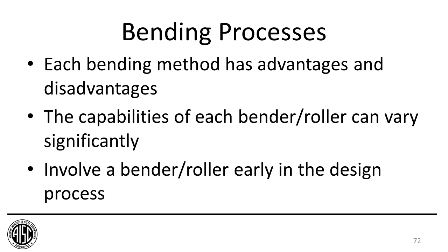It's pretty important, especially if you have something that's a little out of the ordinary, or if you have a very tight radius that you want a member bent to. You want to involve the bender roller early in the design process, hopefully in the conceptual stages.